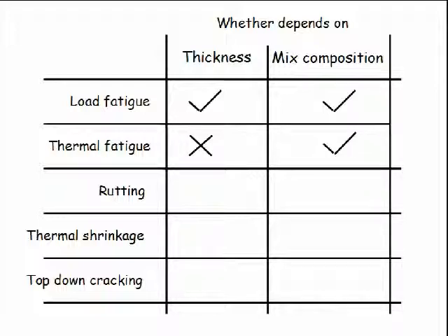If you argue strongly that thermal fatigue is indeed related to thickness, I'm going to agree with you, because it's just how I'm arranging this in the pavement design. So rutting is related. The thermal shrinkage is probably not known whether it is related to the thickness. Then the top-down cracking, whether it is related to the thickness, is possibly not known. And of course, I can expand these issues further, arguing for and against whether they are related to the thickness, but I am skipping that in this presentation.